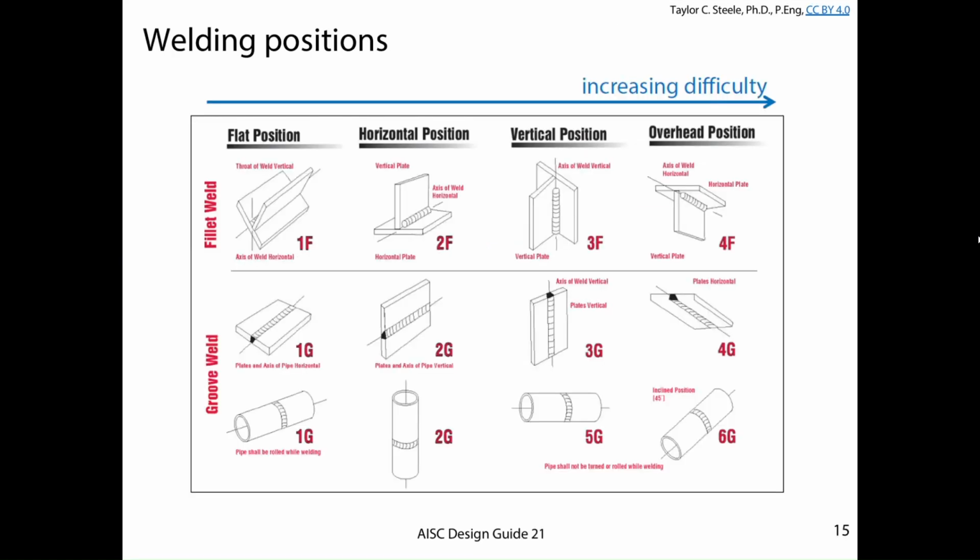One of the things you should always think about as the engineer is construction. If you understand how welding happens and how welders do their welding, you will stay away from difficult specifications. The easiest thing for a basic welding novice to do is to weld in the flat position. The flat position basically just means you take the pieces of steel plate and put them so it's a perfectly flat weld. The weld material is not going to spill off to one side. You don't worry about the molten material sliding. It's the easiest weld. You weld and you're done.